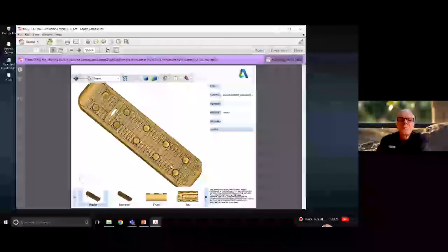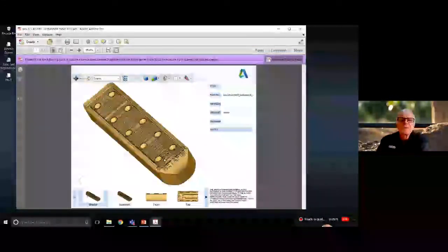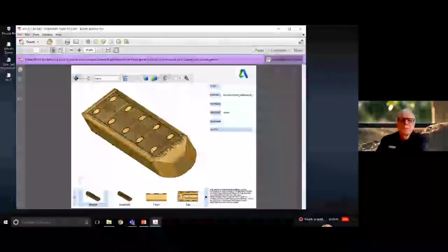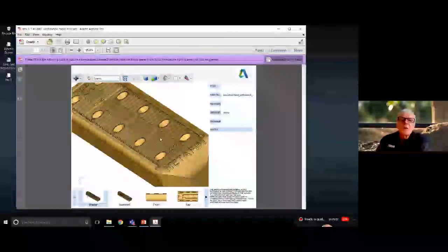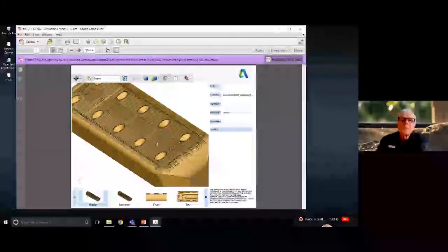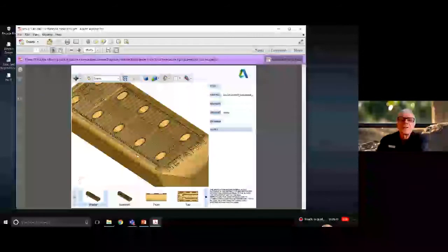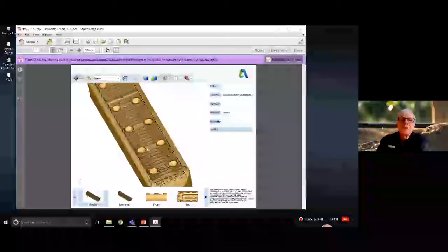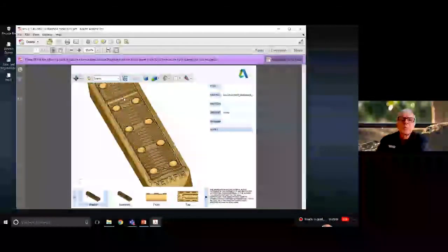So let's see the intricacies of how this actually works. The water will flow from where I'm pointing to this channel here, which runs down here, and it'll flow to the right, going into this channel here. And from there, through that channel, it'll make its way down this channel to the inlet to the dripper.